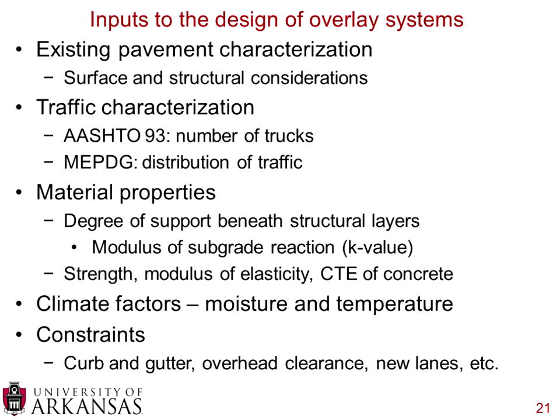Then finally, what kind of constraints are you looking at? Do you need to use a curb and gutter? If you're using curb and gutters, then the profile of your road becomes very important. Are you concerned about overhead clearance? If you're putting this on a road that has a lot of bridges going over it, you may need to do some considerations with how thick this overlay is in order to maintain proper overhead clearances.